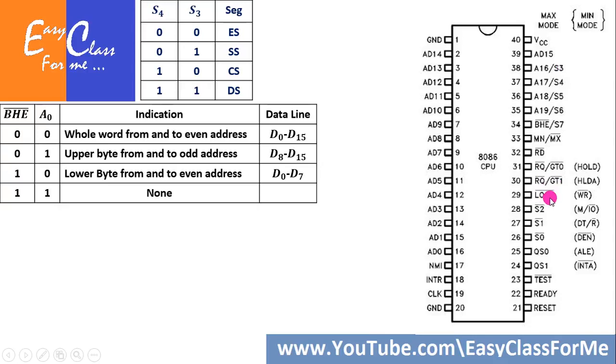When the microprocessor is doing some critical tasks, it is not able to provide its address and data bus through these request grant pins. So this lock pin is used to indicate that the microprocessor has locked its internal data and address buses and they are not made available to the external world for usage.